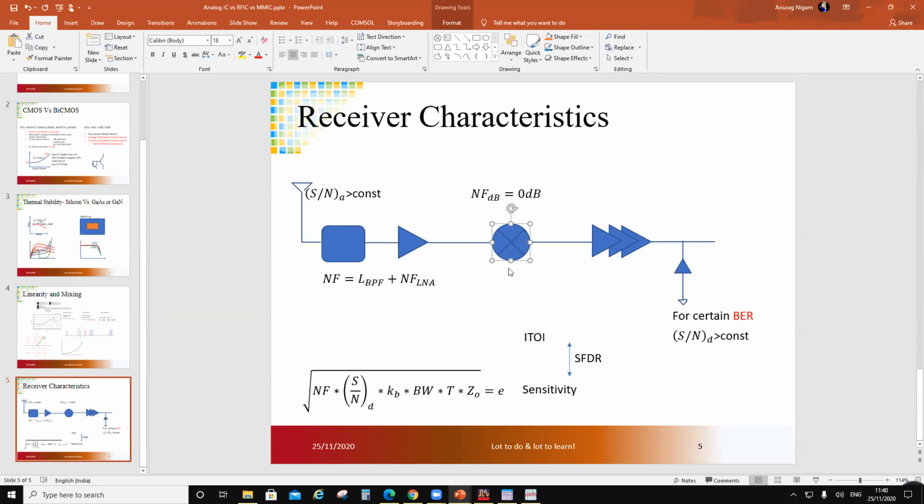Okay, because the mixer, let's say, is again a Gilbert cell. So it would have a compression point, right? That will be decided by the size of those transistors, as small as possible that you can do. So let's say if you do a very small size of those transistors and you compromise the entire conversion gain, then that would be what your mixer can tolerate.